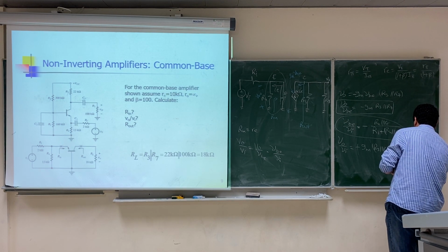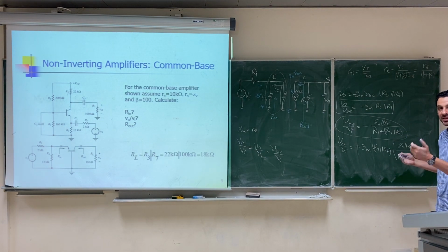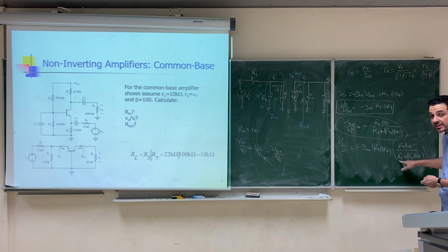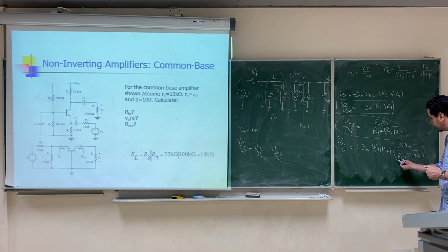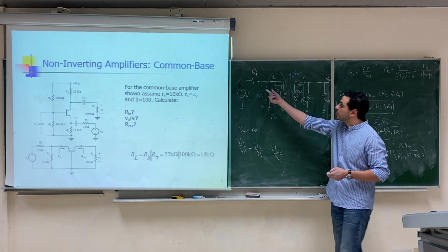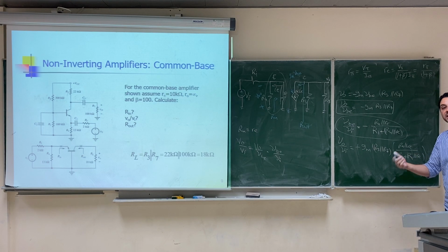As you see here, again, one of the properties that we saw in this example and the previous example is that we have Ri, the source resistance, the input resistance of the source here. If the input resistance of the source is high, the voltage gain will be low; you will get a very small voltage gain.